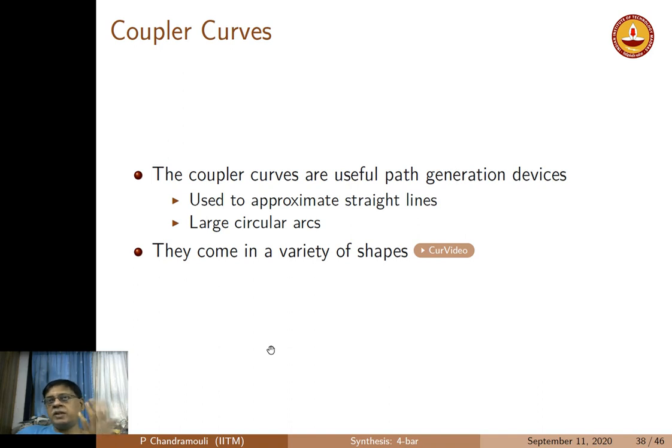So, to summarize, what have we seen? We have seen how to use a 4-bar, basically a crank rocker design, given a certain crank rocker rocking angle between the two extremes, and alpha, which dictated a time ratio. We had a positive alpha and a negative alpha. I've explained that negative alpha. Some of you had asked nice questions, and I think the text will undergo some transformation to reflect the replies that I have made.